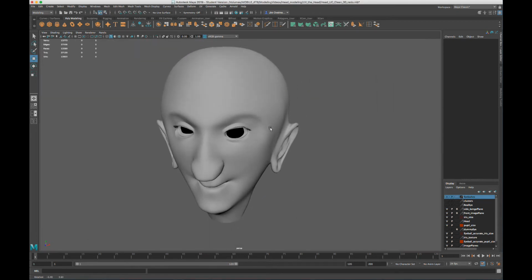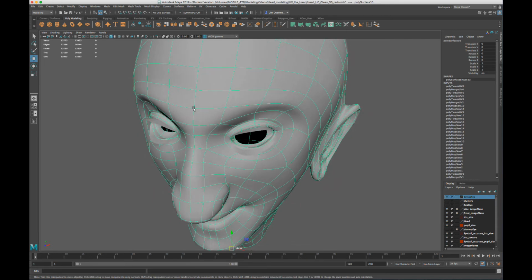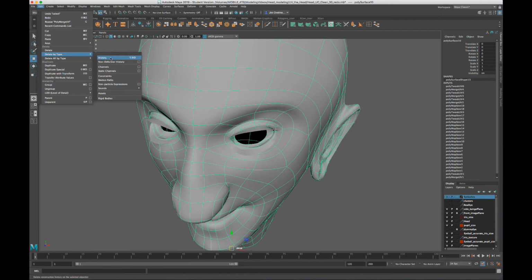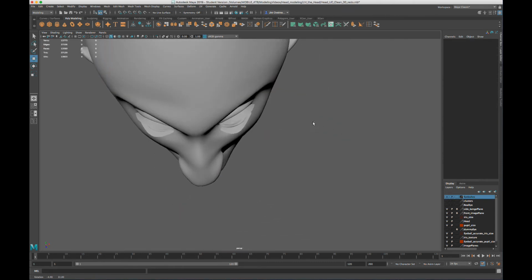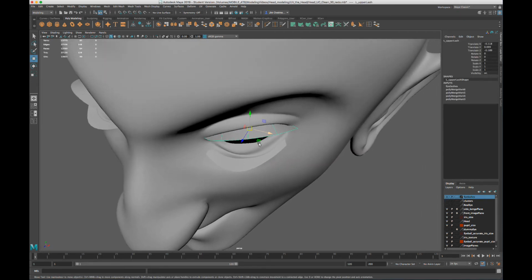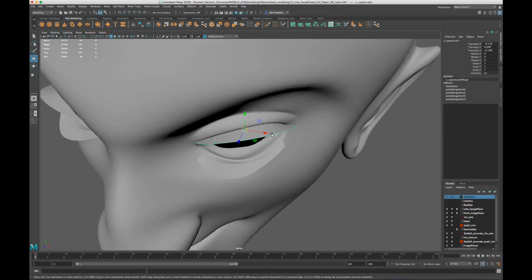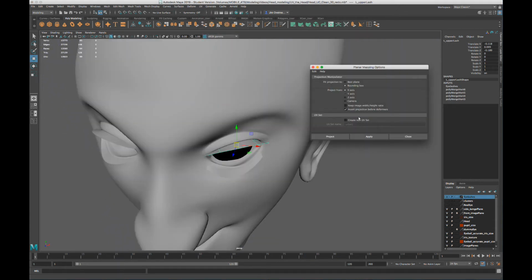Okay, now for the eyelash UVs, we're going to prep them separately. Remember, we detached them from the head. By the way, we finished with the head UVing. We can delete the history. All right, we have this separated. We are going to give each one of these, each one of the four, upper and lower, their own planar projections. Just take the top one here. We're going to planar and option box. Make sure you select the Y and click apply.